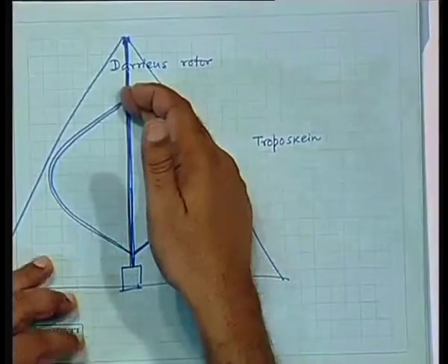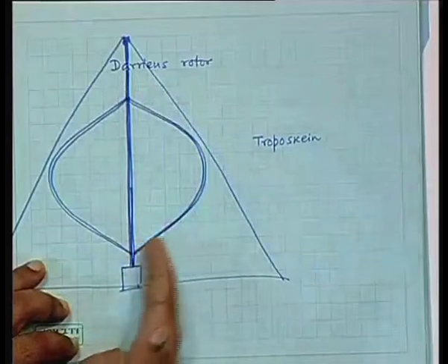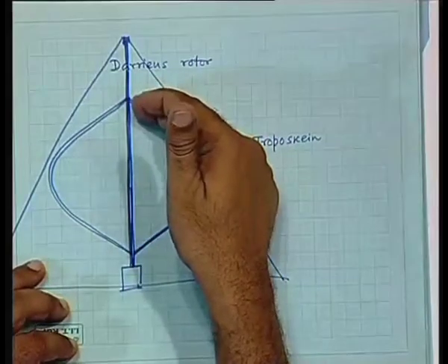That's all. So if you build into it a strength along the length of the blade, then obviously it becomes more stable. It's very difficult for such a blade to break, which is not true for horizontal axis wind turbines. There can be forces which can make those break, but here nothing will happen.